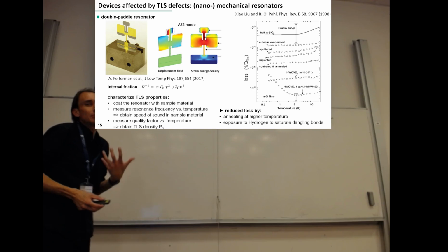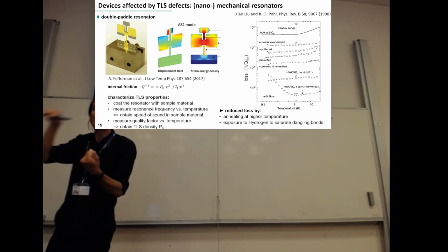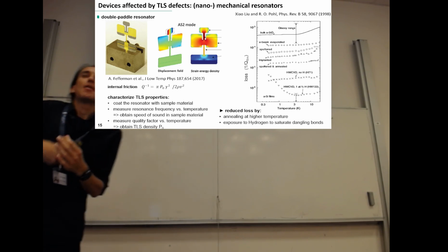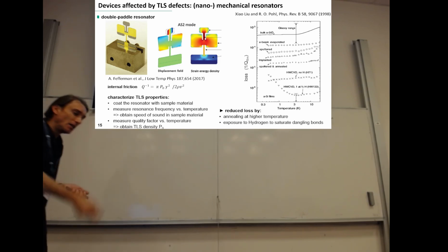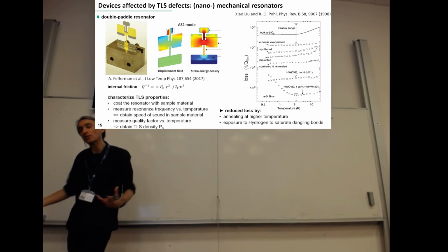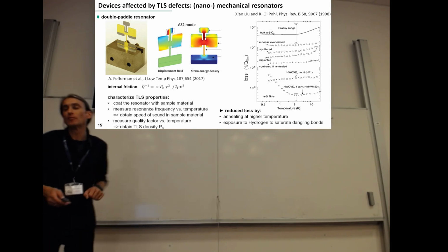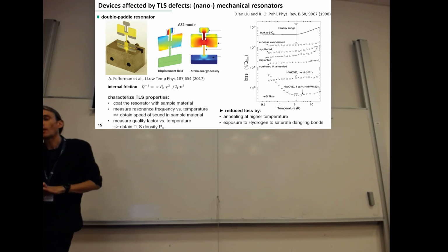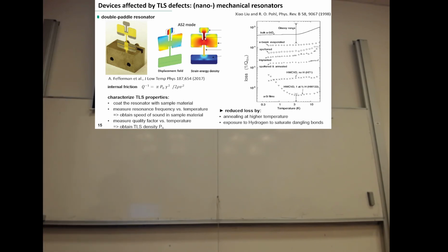And here the idea is actually that with the hydrogen you can saturate dangling electronic bonds, which exist in the amorphous materials due to the large disorder. And this not only limits this lengthening of this bond, but also it constrains the material further. So you have a higher density of this material, which just restricts the motion of these atoms more compared to the unsaturated material. Yeah, and so these kinds of insights you can get with these resonators.